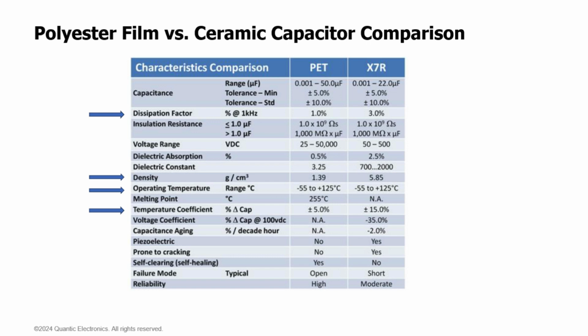Also important to note, more stable dielectric materials exist in the NPO side for dielectrics. So I've been focusing on X7R dielectrics, which have high cap density, but are not necessarily stable. They have a higher coefficient, if you will. There do exist alternatives in ceramics. The disadvantage here is that those more stable alternatives are also much higher in size.